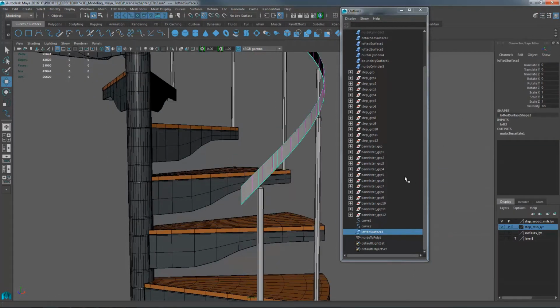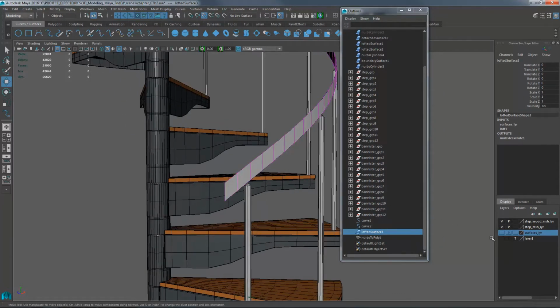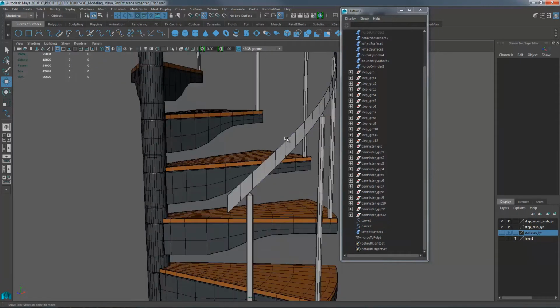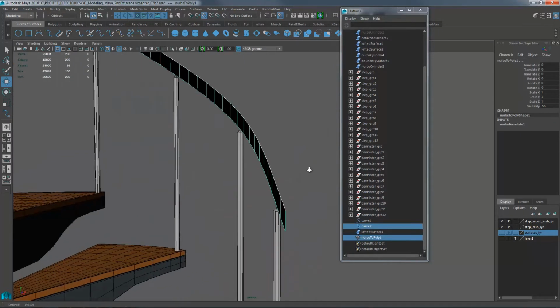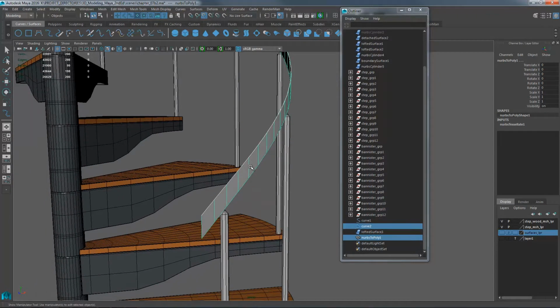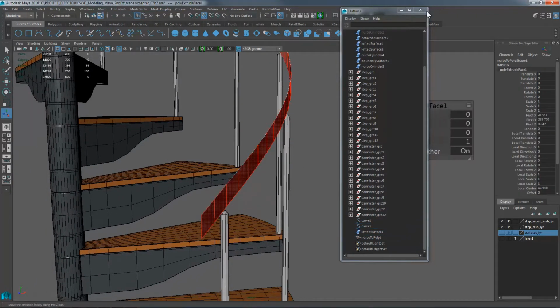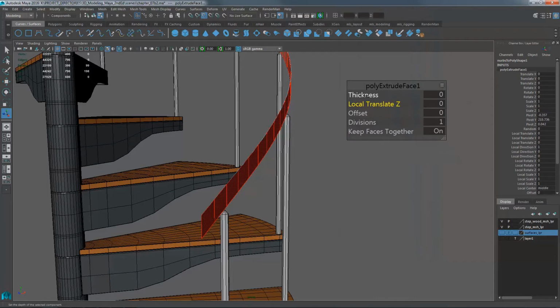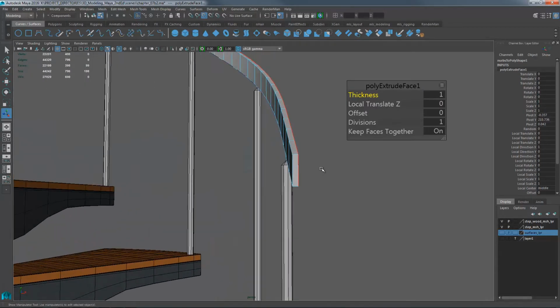Select the lofted surface. Don't delete it or anything of this sort. Just place it on that layer that has surfaces. Say add selected objects, and it will hide because that layer is hidden. And then let's thicken this wood strip that's going to become the wood. So that would be Control E. Don't need that right now. And let's thicken it. Let's go with 1 unit for 1 centimeter.